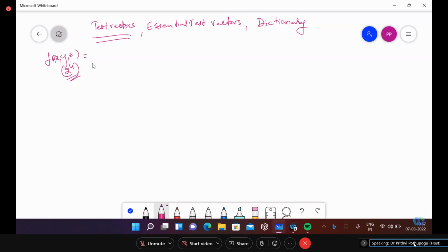There is no need to go for testing again or release it into the market. Say out of 2 power 4 combinations, 1 or 2 combinations give an error, then you have some amount of efficiency. So what are those 1 or 2 combinations for which a user has to test the design when using it? That is a test vector. We say vector because it is a combination of inputs.